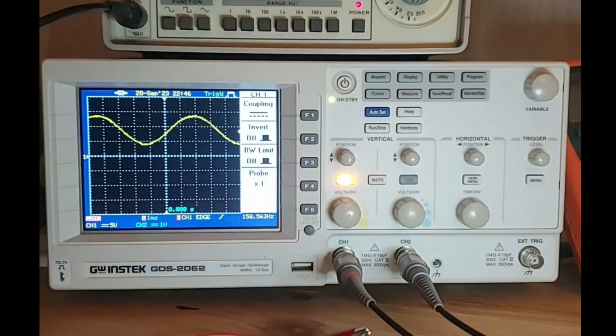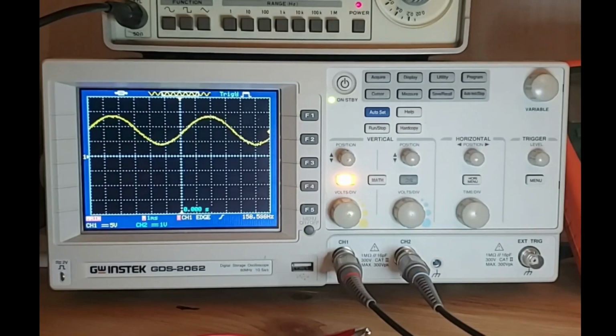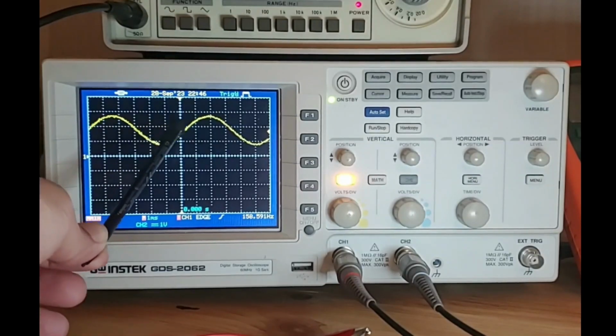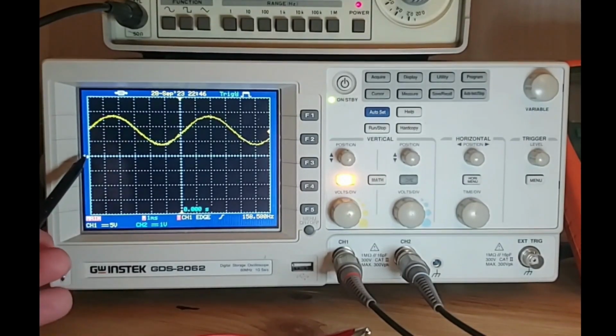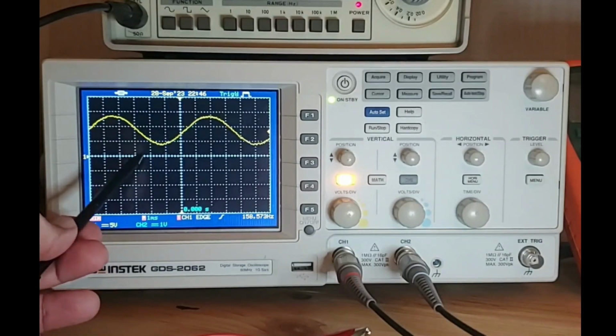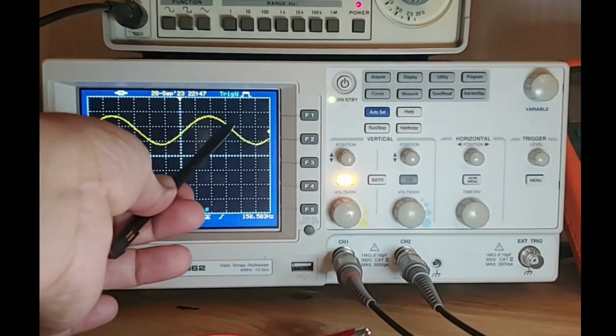let's say 5 volts per division, and let me remove this. So you see now this is the voltage that the function generator is producing. I have a sinusoidal, but this time it is riding on a DC level, and the DC level is somewhere over here, as you can see. So the signal remains positive all the time. It never goes below zero, because zero is over here, as you can see by this arrow, channel 1. This is the zero. So the signal doesn't go negative. It is always positive. It's a sinusoid which is riding on a DC.